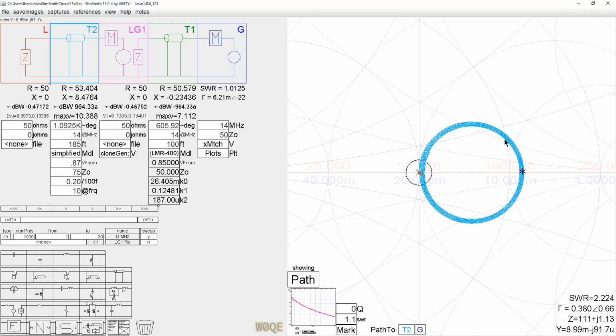We don't know what impedance we're going to end up with. Clearly, the impedance we end up with is a function of the length of this and what frequency you're on. So we might need a tuner here, and that tuner might not be needed here. It would be needed here perhaps if the antenna didn't have very good SWR bandwidth and you wanted to operate in part of one of the bands where it didn't work well. But in general, let's assume that the antenna here is a good antenna and we don't need a tuner. We do need a tuner here.